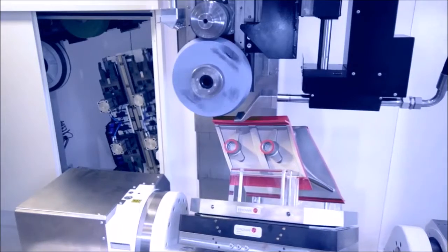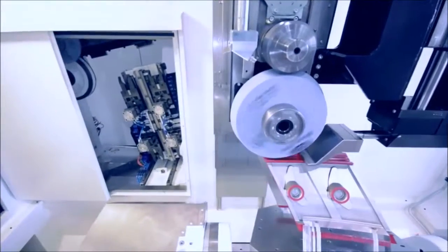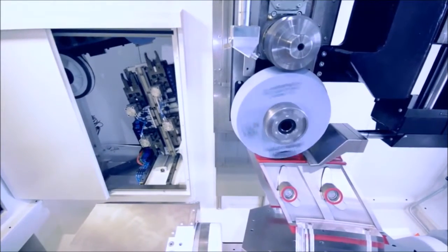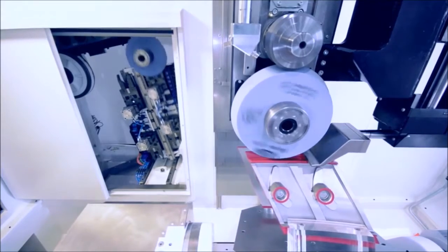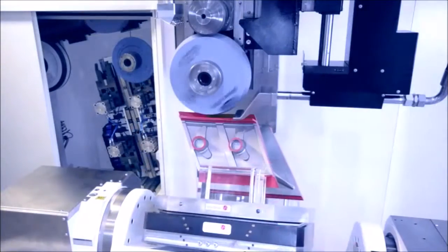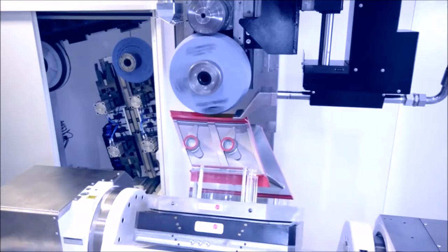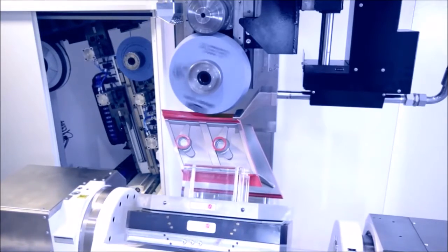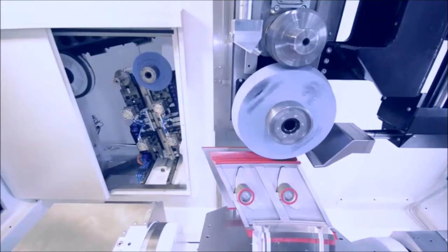A more exotic type of grinding is creep feed grinding. It is used to remove much larger amounts of material than conventional grinding, by increasing the depth of cut and decreasing the feed rate proportionally. This process is used to better preserve the surface of the workpiece or create curved surfaces for plane wings or turbine blades.